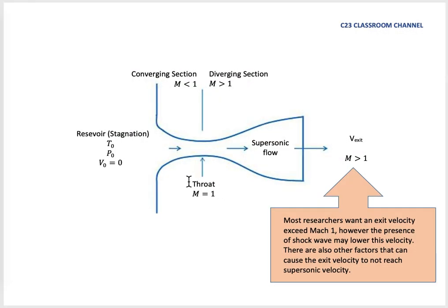This is the common phenomenon in convergent-divergent nozzles. So if you have a question about a convergent-divergent nozzle, you may take Mach number equal to 1 in the throat area. If you give more pressure, the velocity in the throat will not increase more than 1.